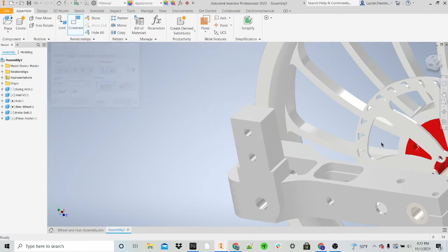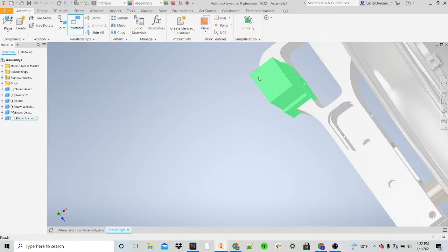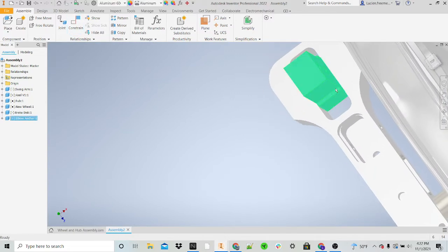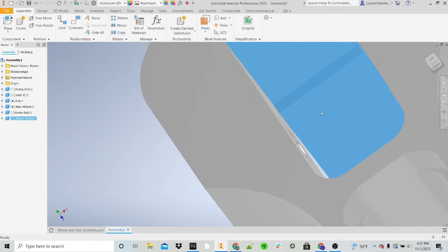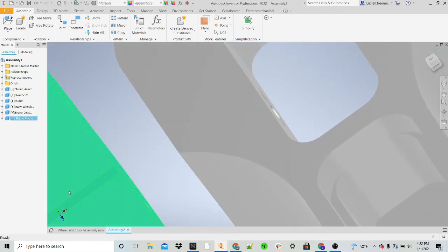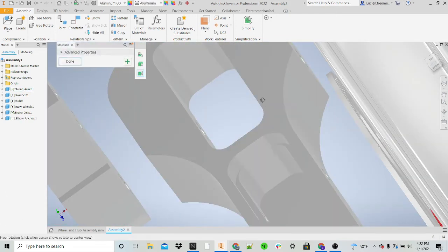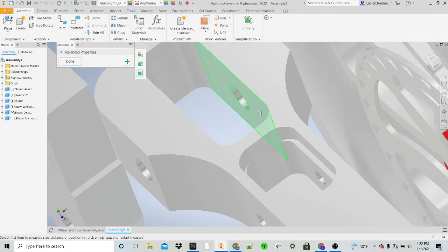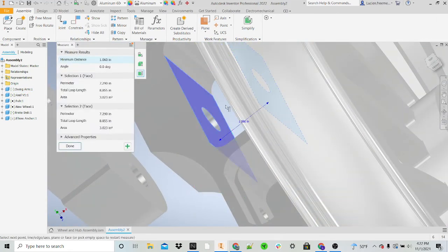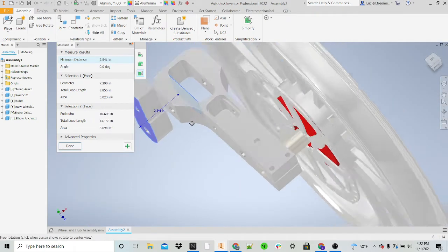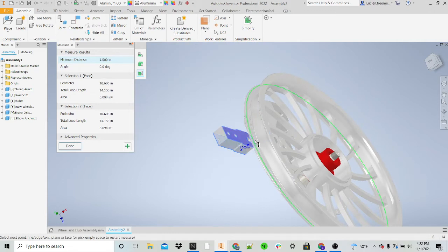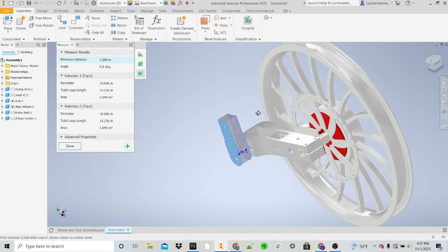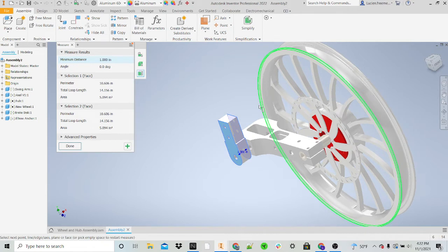And so there's something interesting with this part I'm going to show you here. This piece is built to be just a tiny bit smaller than the actual piece because it's got to rotate. And so I'll prove it to you here real quick. If we take the measurement, so you press M as a shortcut to measure, take that surface to that surface, you can see it's 1.06 inches. And now if you come over here and you measure that surface to that surface, that's just 1 inch. So it's about 6/100ths bigger, which means if you divide that by 2, it needs 3/100ths of space on